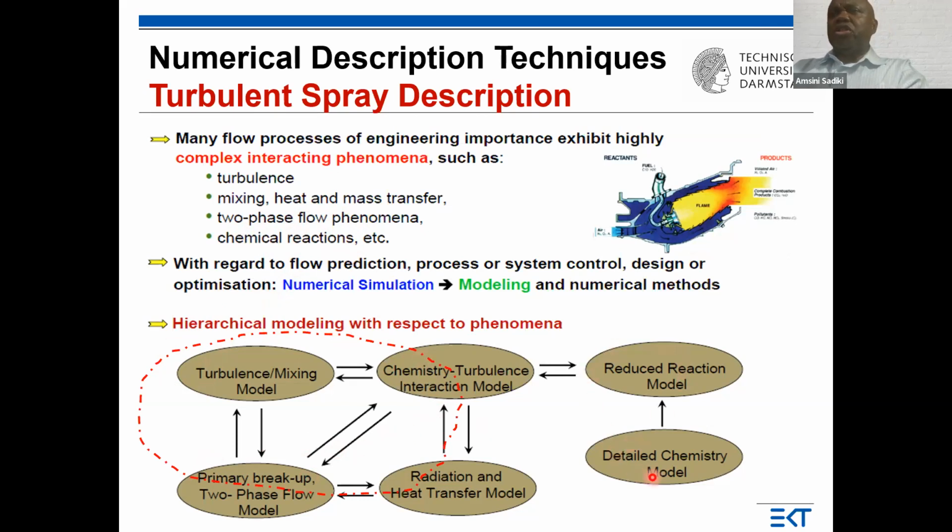This was shown also yesterday. I recall the reduction from the detailed chemistry to reduced chemistry, to make it available for the LES or RANS calculation with the lookup table based on FGM or on the flamelet progress variable tabulation.